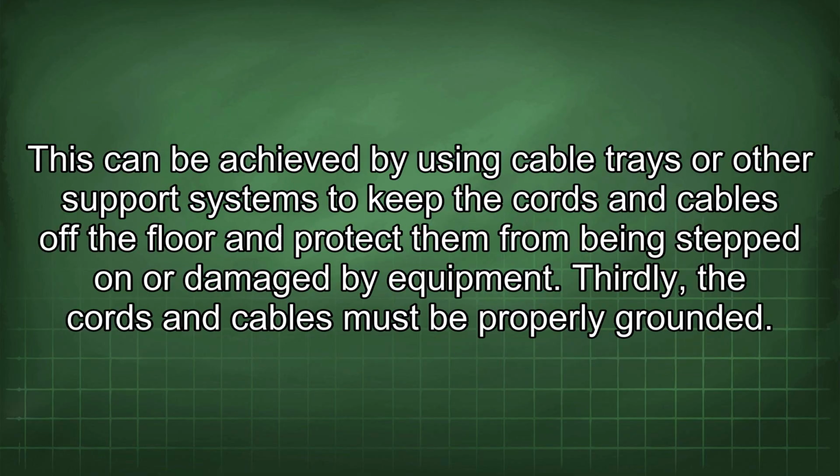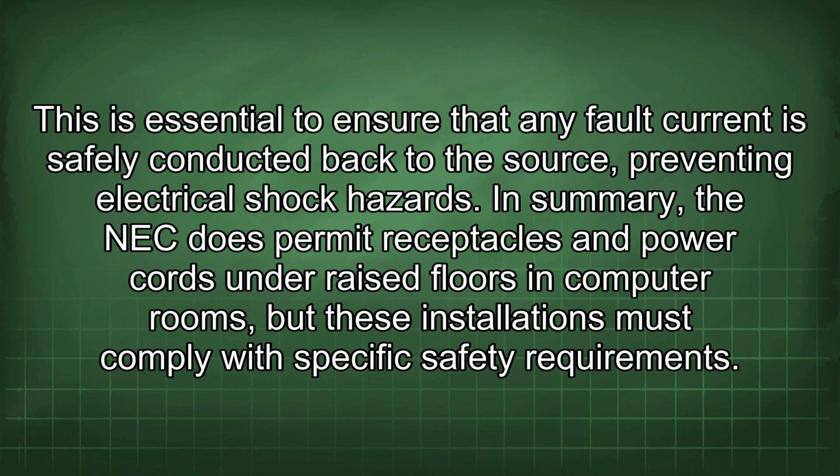This can be achieved by using cable trays or other support systems to keep the cords and cables off the floor and protect them from being stepped on or damaged by equipment. Thirdly, the cords and cables must be properly grounded. This is essential to ensure that any fault current is safely conducted back to the source, preventing electrical shock hazards.